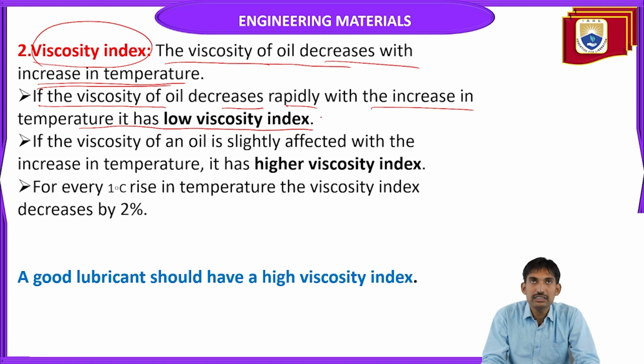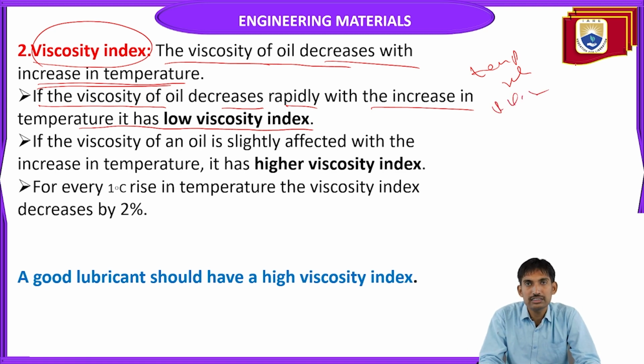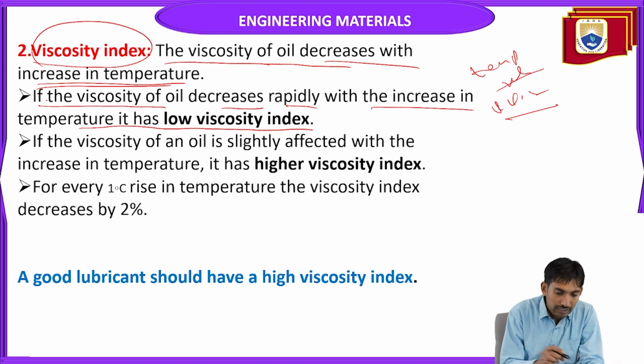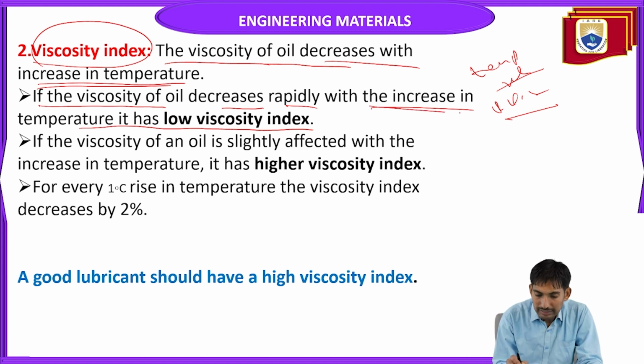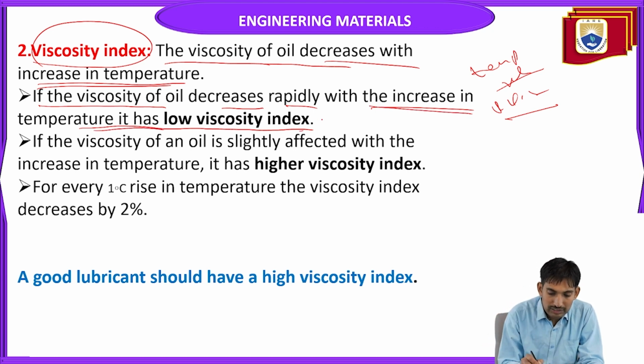What is meant by viscosity index? It is a relationship between temperature and viscosity. That is called viscosity index. The viscosity of oil decreases with increasing temperature. If the viscosity of oil decreases rapidly with the increasing temperature, it has low viscosity index.